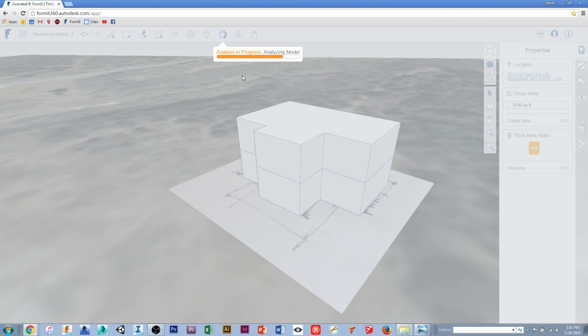Grabbed that as an image, again, didn't send it through a scanner or anything that technical. I just used my phone, snapped a quick picture of it, imported that as a background image through the import tool right here. Set the scale of the image correctly. I had to do that twice in this particular case, but set the image. Built the massing model using the pen tool.